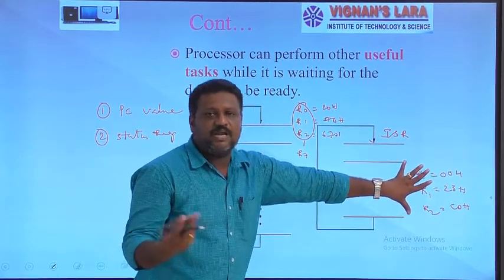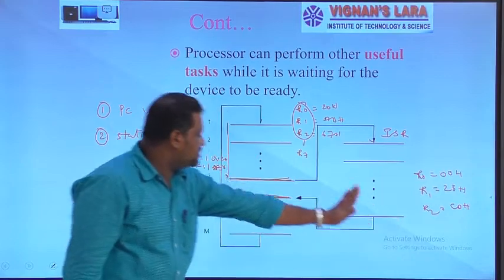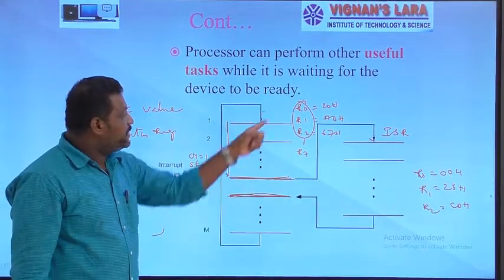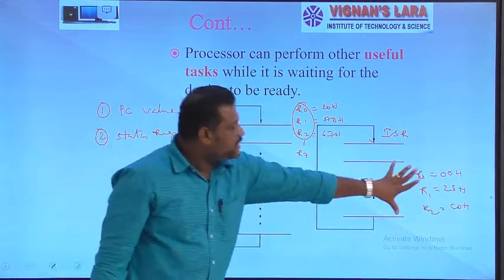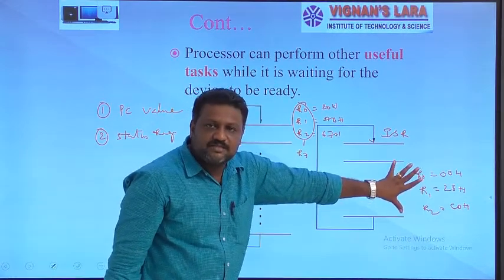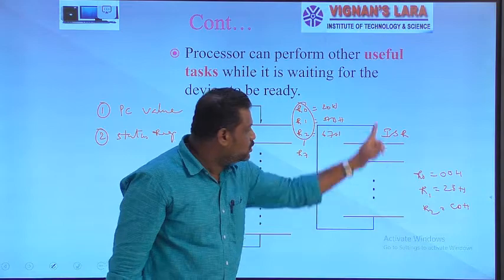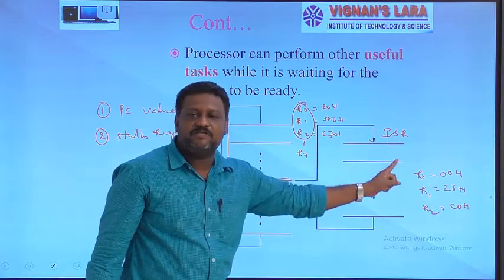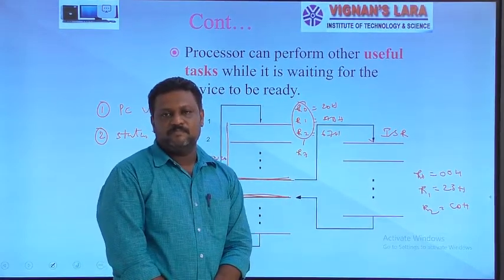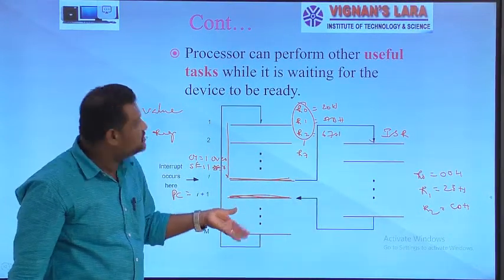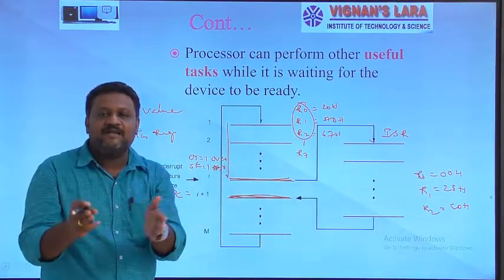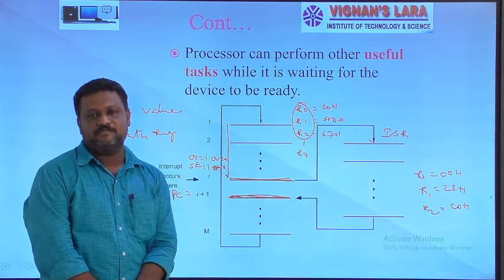Right? Then what happens? If I come back from this service routine to this, the previous case R0, R1 and R2 values are different compared to the values that exist in R0, R1 and R2 after execution of the interrupt service routine. So, if I continue with these values in the execution of the rest of the instructions of this program, at the end I may get wrong results.